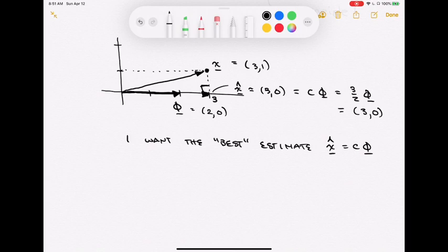The math that we got says that the orthogonality principle tells us what is best. The orthogonality principle will give us an error, E, that is minimized by projecting X down onto phi, through a dot product, and then dividing by the size of phi squared.